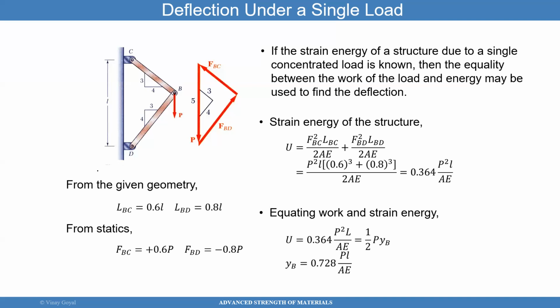You choose. So I apply the load P going downwards, so I'm going to measure it downwards to make it easy for me. And if the load is going downwards and the deflection is going downwards, the energy is positive. Now, if I say that this is going upwards, then this should be negative 1/2. I rather keep it all the same direction and it's easy for me. You agree?